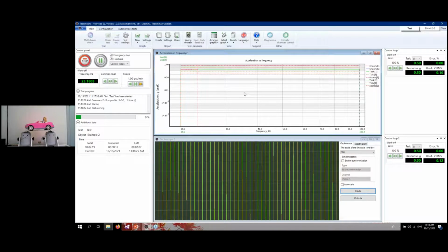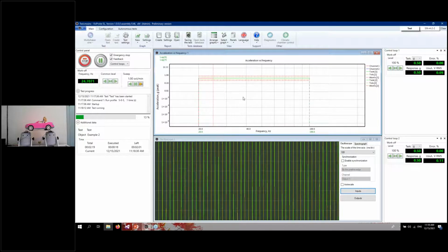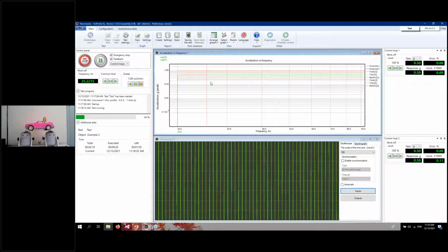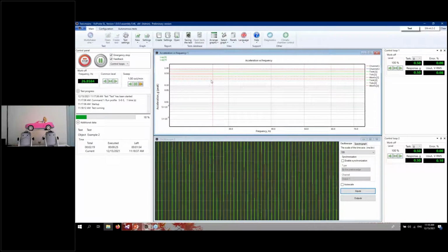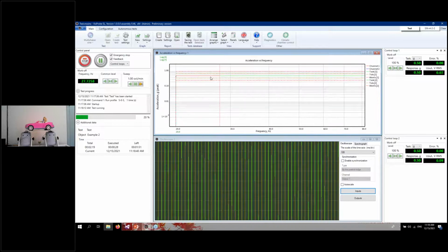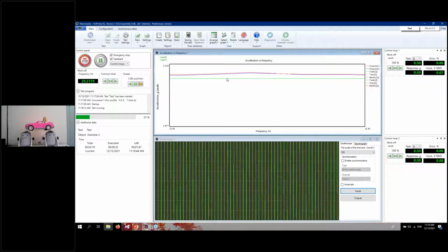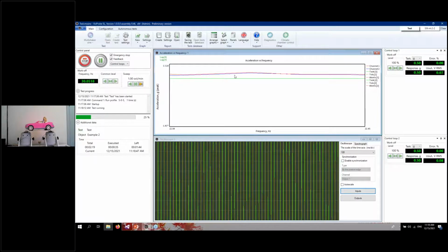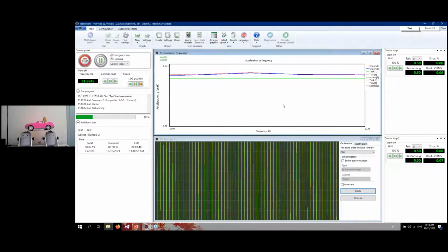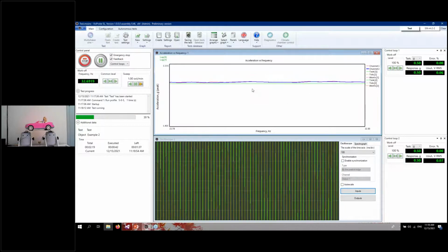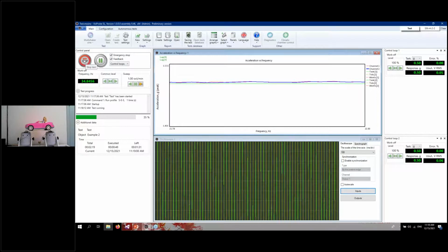Let's wait for 40 Hertz frequency, and we will continue with the next test. I hope you see it. You can see that we're running our test really near to our profile. Here you can see the task and our channels data. Now I think we can stop the test and continue with multi-shaker random test.